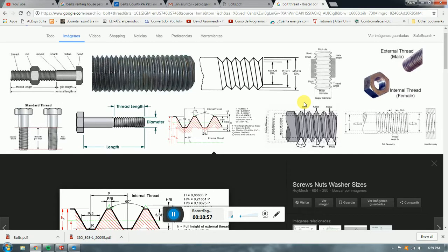However, I'm not 100% sure, but I recall from Shigley's mechanical design book that statistically it does not always break in the thread. I think it was 65% of the times it breaks in the thread. Then you have another 35% that breaks in the head or in the shank or other areas, I guess based on the manufacturing process or other reasons.